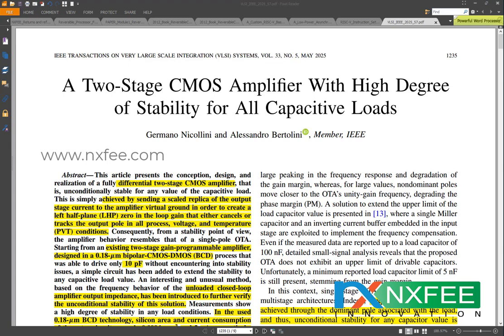The novelty of the work is that we use the natural short channel behavior of the 22 nanometer and 45 nanometer devices to enhance the gain instead of suppressing it, which helps in reducing power without sacrificing performance.